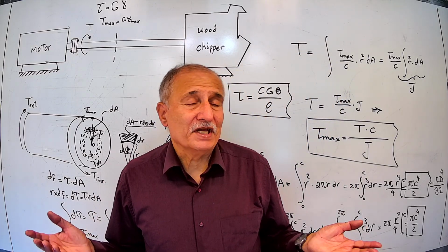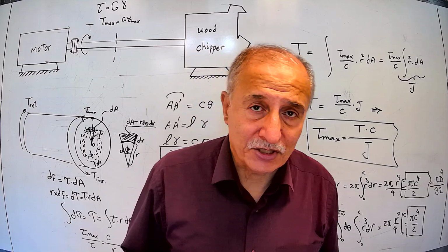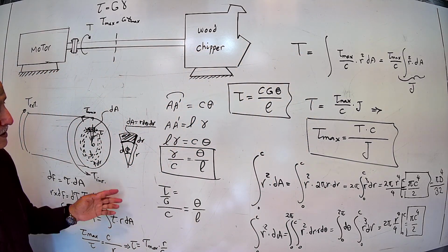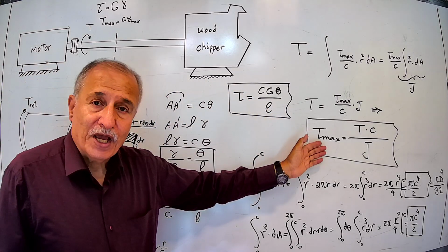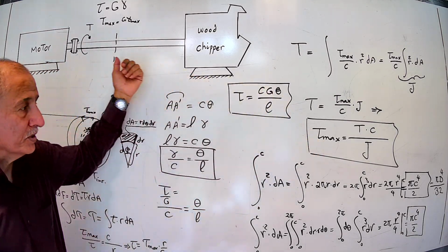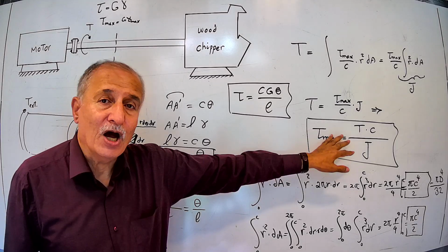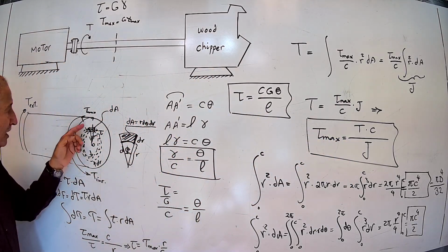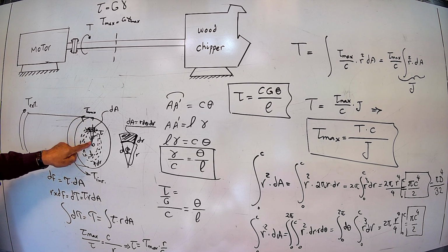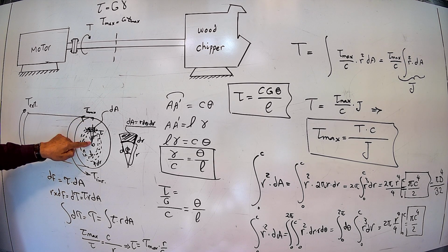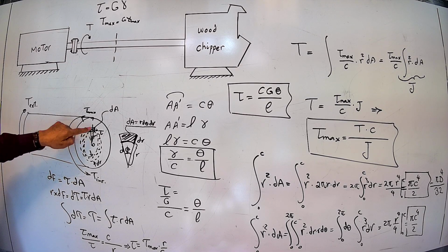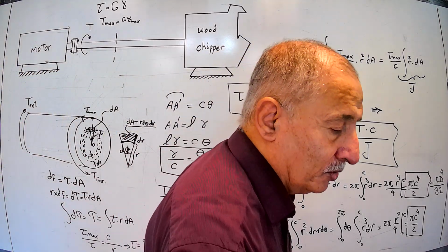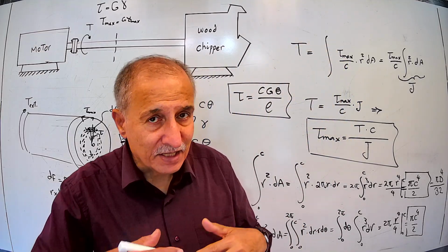They call it the polar moment of inertia of the area, which is circular here. Then, the shear stress due to torque is maximum at the outer surface, and when we go from the outer surface to the center, we approach 0. For any points between 0 and C, if you want to calculate shear stress at any point inside the cross